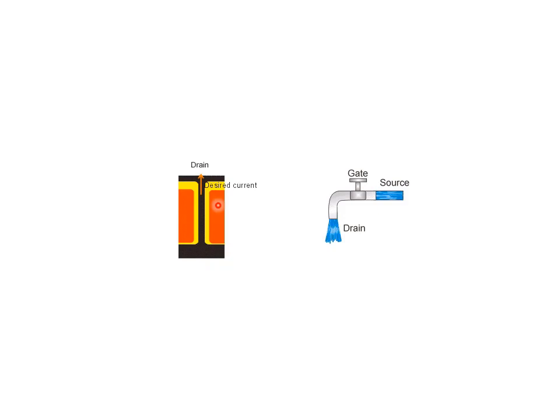We said the barrier potential is something we cannot control, but the depletion layer, we can expand and we can minimize. How? By applying external voltage. So it means this depletion, this yellow area here, guys, can be minimized and can be maximized. So we can maximize this depletion layer until we can actually close the channel.